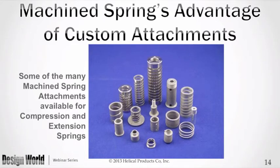Basically, the feature here that is really important is the attachments. And these springs here are predominantly either extension springs or compression springs. And you can kind of look at the group and see which ones are which. The extension springs will have bosses on the ends or threads or something so you can get a hold of it. And the pure compression springs, or just compression springs, do not need any special attachments. So as you look around there, you can see those two cases.